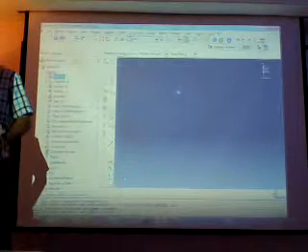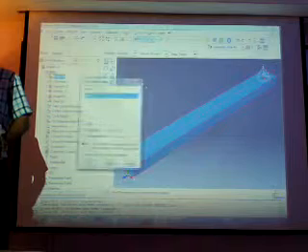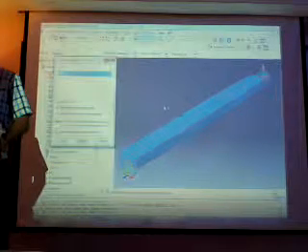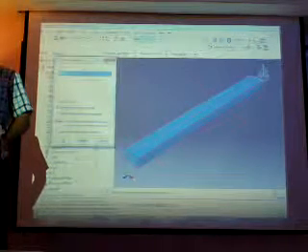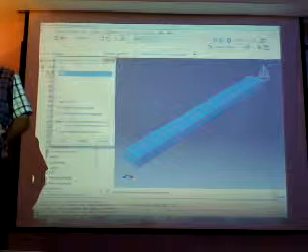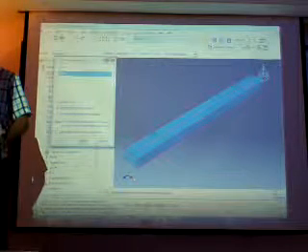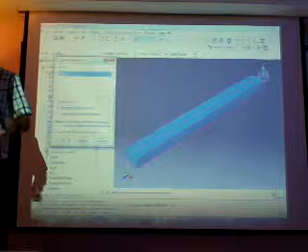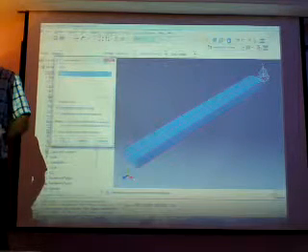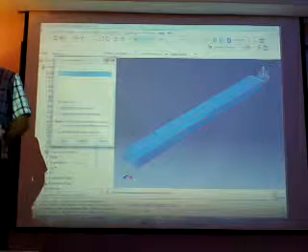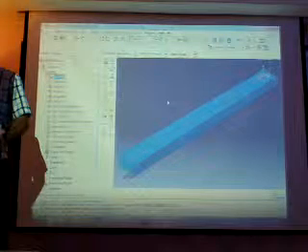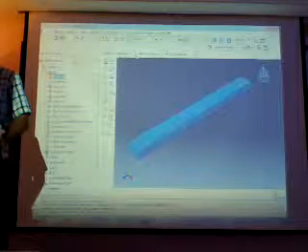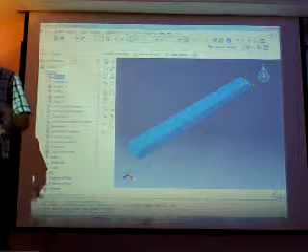The next module is the assembly. We should create our instance. Here we have 2 important options, dependent and independent. We always take dependent because we want to mesh each part individually. So that's okay. Assembly is a necessary part for all Abaqus models.